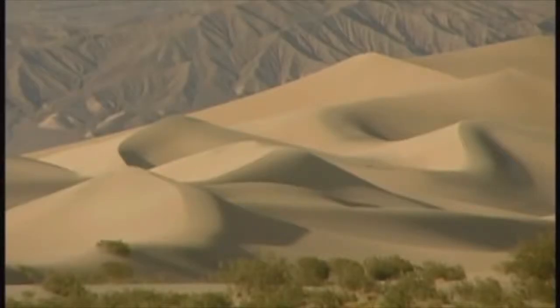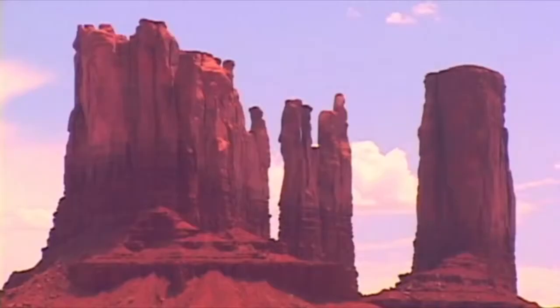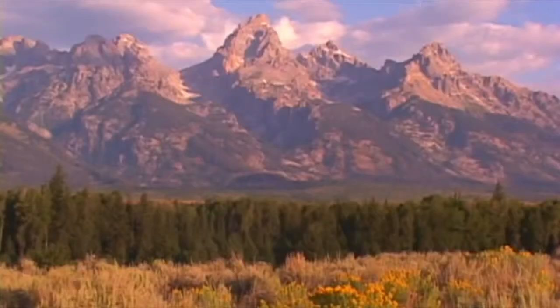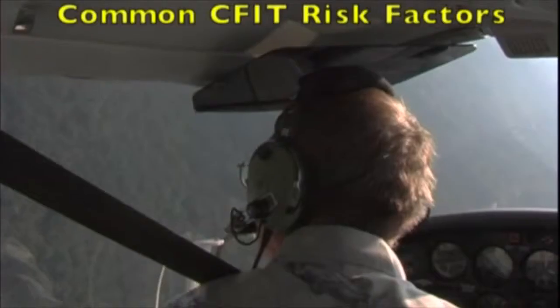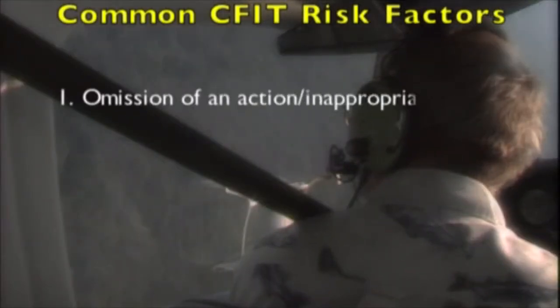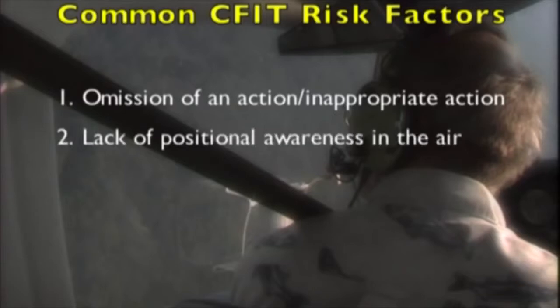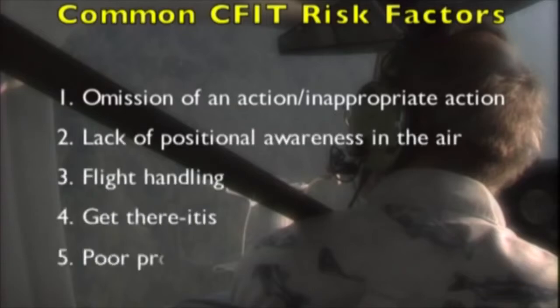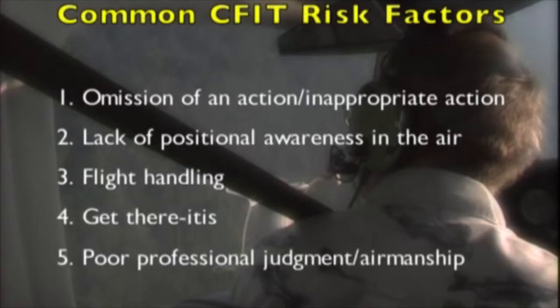Take an environment fraught with CFIT risk. Add pilot error and watch out. Let's look at the major risk factors and the traps they present. There are 5 common risk factors: omission of an action and/or inappropriate action, lack of positional awareness in the air, flight handling, get-there-itis, and poor professional judgment and/or airmanship.